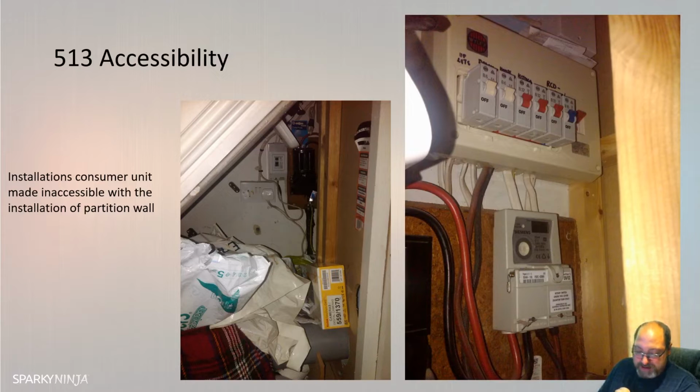Moving on to accessibility. Short and sweet. Except for a joint in cables where section 526 allows it to be inaccessible, every item of equipment shall be so arranged to facilitate its operation, inspection and maintenance and access to each connection. Such facility shall not be significantly impaired by mounting equipment in an enclosure or a compartment. Everything must be accessible for maintenance unless it's been designed to be maintenance free. This is a